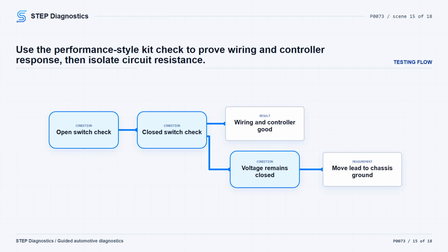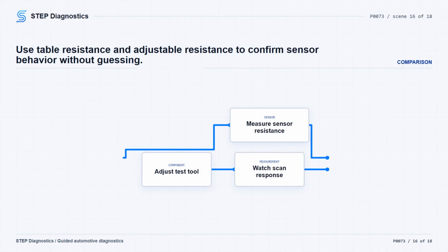If the resistance measurement does not catch it, carefully inspect the connectors in that circuit path for spread, dirty, or corroded terminals. If the circuits check good, keep separating the fault between the sensor and the controller instead of guessing. When a temperature table is available, use it to verify the sensor and controller response. The sensor table is held to +/-10%.